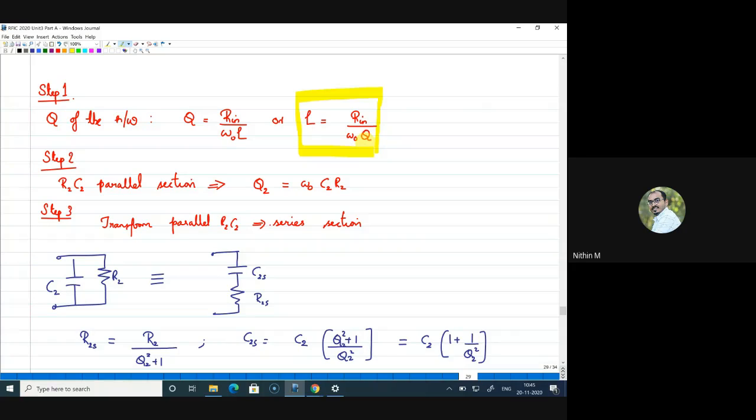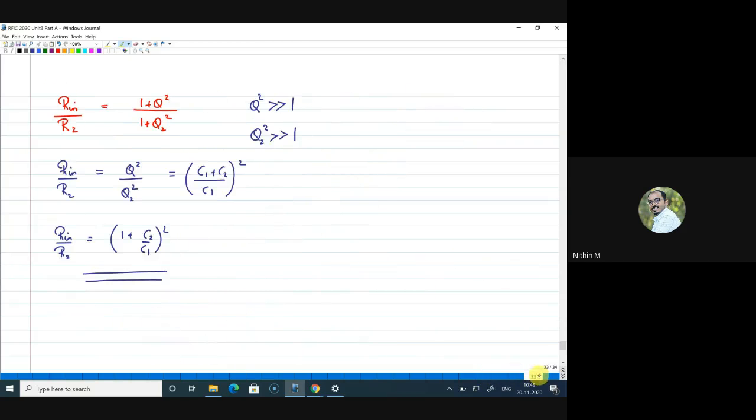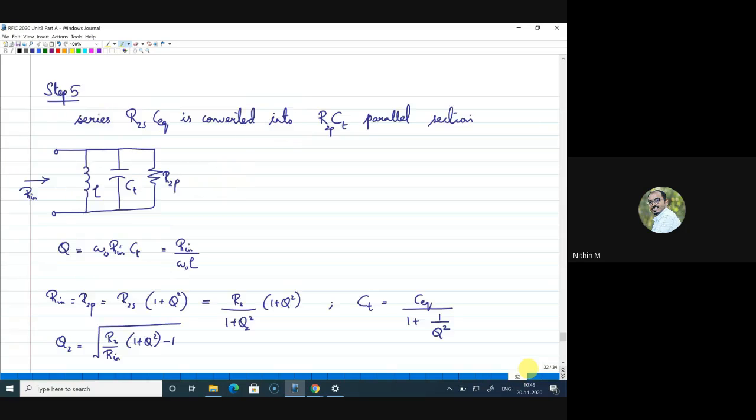Yeah, with that I think you will go ahead and find this value. Let me just listen to you guys. Okay, L is coming around 19.89 pico. Can you check again? Is it 19.9, or 0.199 Henry, right? So it should be 199 pico, right? Yeah, L is that. Go ahead and find the rest of the things.